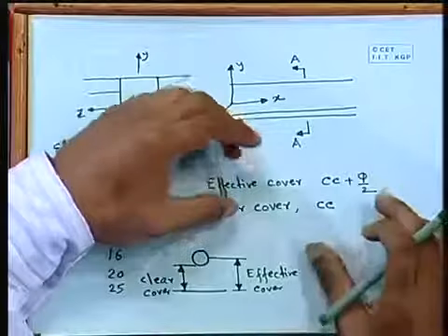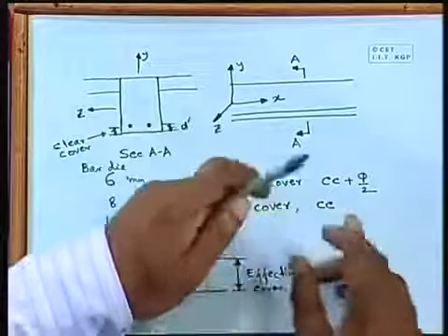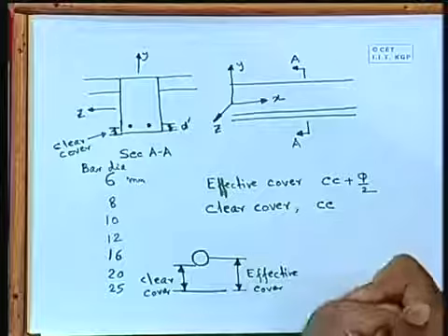Now coming to this particular point, why do we need clear cover? One important aspect is the corrosion of steel, so that the steel is not corroded. That is one aspect, and there are many others we can find. From the environmental aspect, that is the major one we can consider: we have to give proper cover, we simply cannot place the steel immediately at the bottom. So that part we have to consider here.